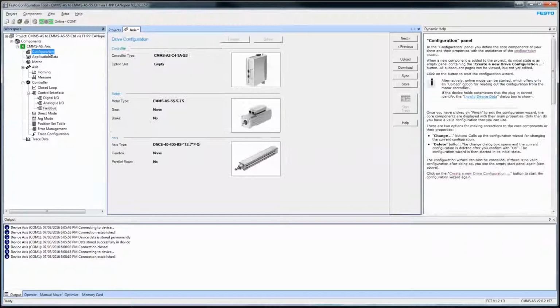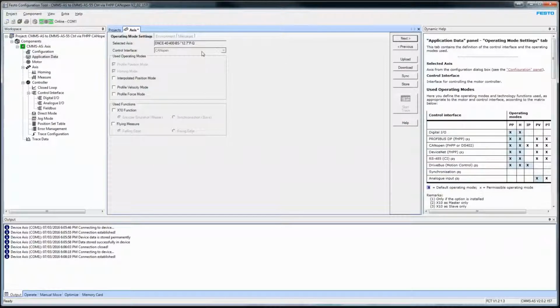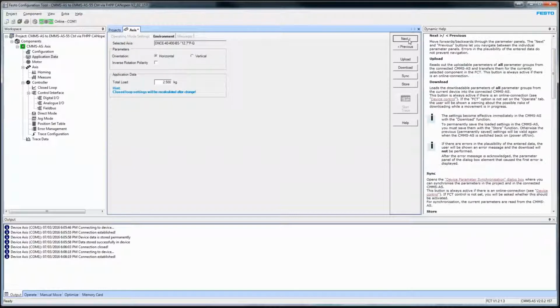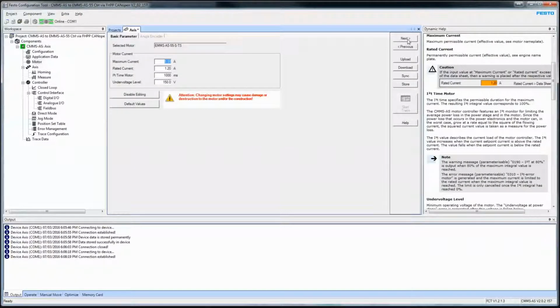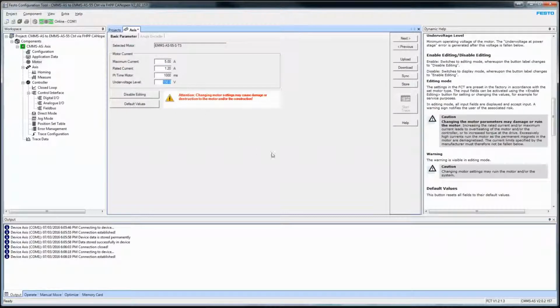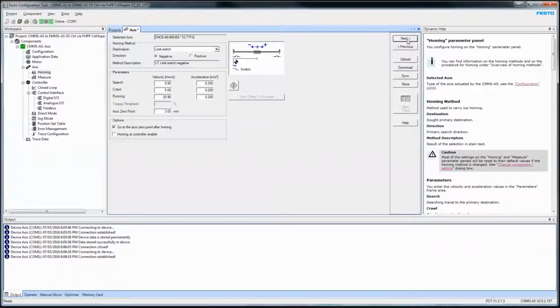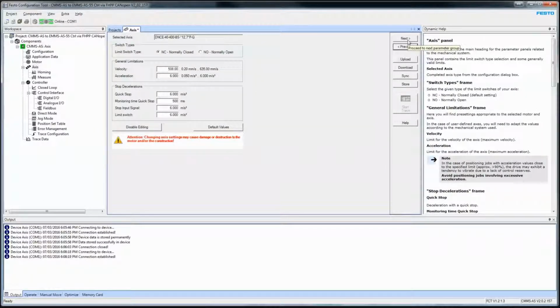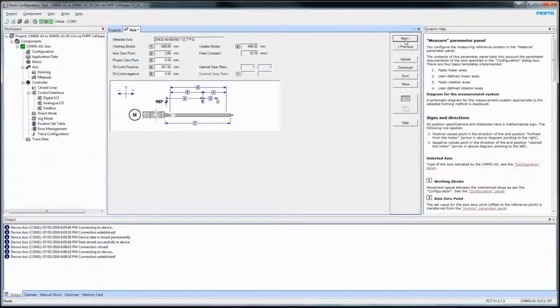And what else is there to tell you? This is what I'm using for controller and motor. CANopen is the configuration. It's important that that voltage is low enough for your incoming, whether it be 220 or 120. Homing is via limit switch.